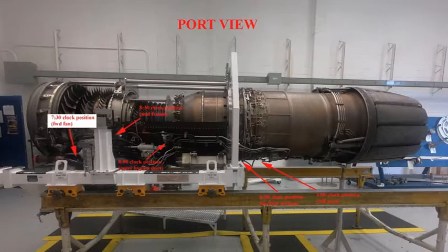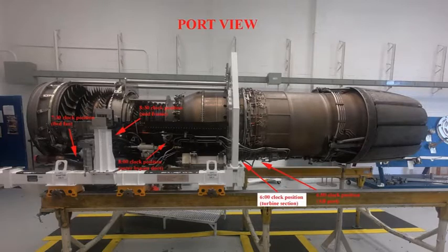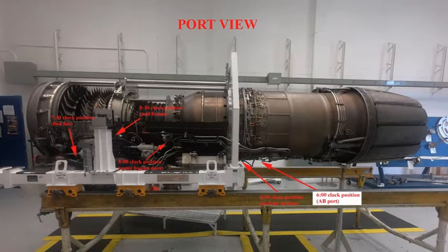Before starting the borescope inspection, remember to have MDART with you, following step by step to prevent damage to equipment or injury to personnel. Here are the borescope port locations from the port side of the engine. First up, we have the 7:30 o'clock forward fan position. Then we have the 8:30 o'clock mid-frame position. Next, we have the 8 o'clock outer bypass duct position. Now we have the 6 o'clock turbine section position. And then finally the 6 o'clock afterburner port location.